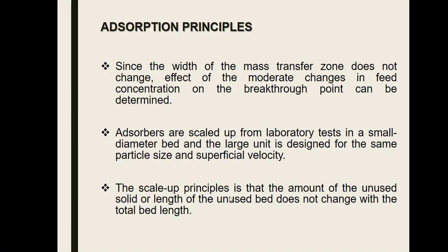Now, the scale-up principle is that, take note of this, the amount of the unused solid or the length of the unused bed does not change with the total bed length. So it's something like ratio and proportion. If you have a length of the bed around 5% of the entire length of the bed which is unused for a particular adsorption process, then whatever is the length of the bed that you're going to design later on, the same proportion of the entire height or length will remain unused.